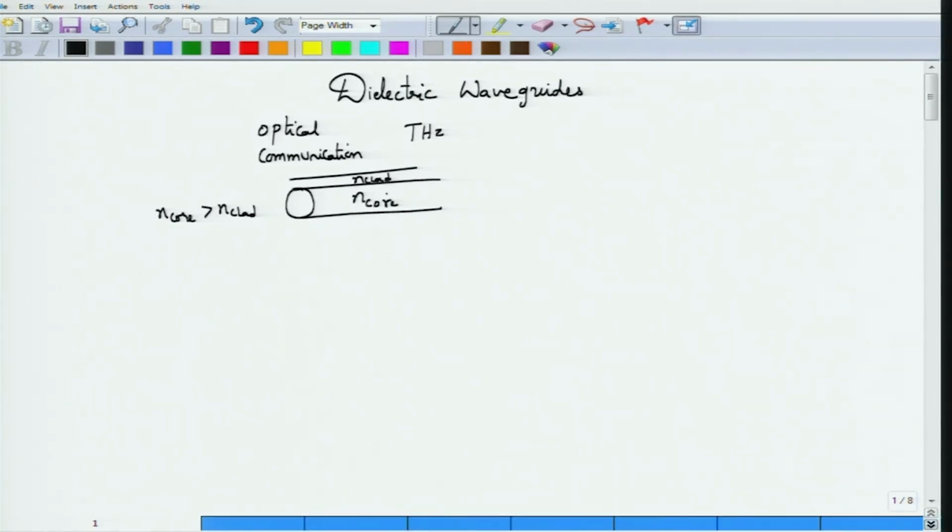And in fact, if you make this rod using silicon or a combination of silicon and germanium, you can show that the losses can be made very small, and this is the reason why optical communications has become widespread now. You can carry information in the form of electromagnetic energy at wavelengths around 1550 nanometer. These are not in the visible range; this is called the near IR, that is, the near infrared region.